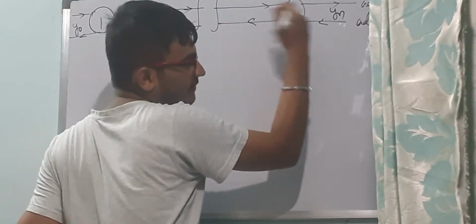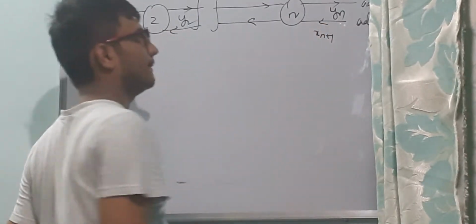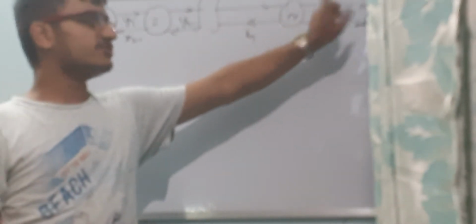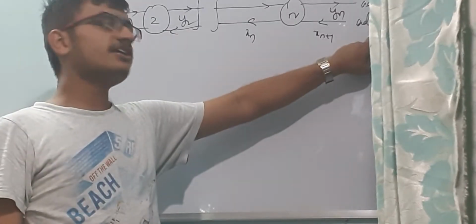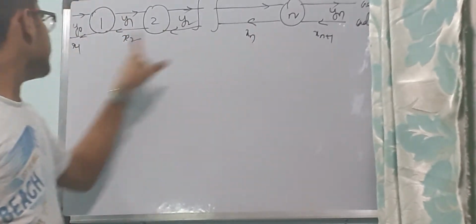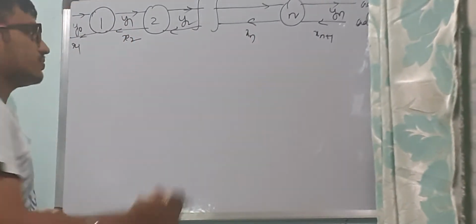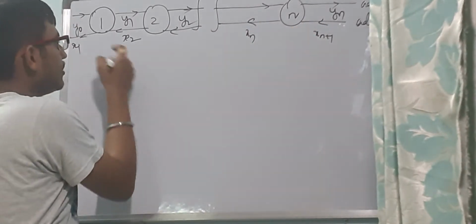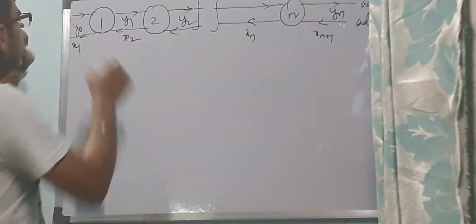So it is entering from the n plus 1 stage, right? So xn plus 1. This is xn, x2, and it leaves at x1. So the initial composition of the adsorbate or the solute is y0, leaving composition is yn, and the initial concentration of the adsorbent or the solid is xn plus 1 and leaving concentration is x1. So now for this entire stage, if you write a component balance, what enters? This is Ls and this is Ss and Ls.